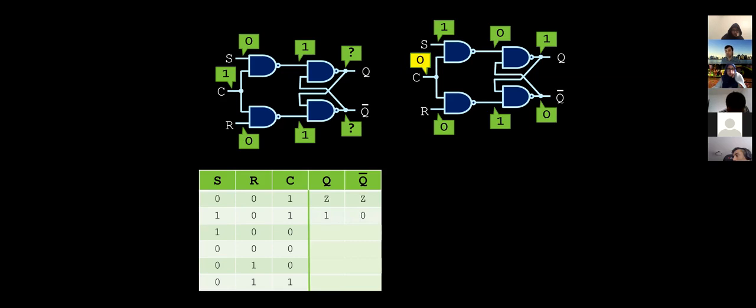Okay, what if I go down with my timing? I go from a positive 5 volts or something to 0. Well, let's see. This 0, 1 is not going to affect this one. This is still 1. So with this 0, 1, this is still 0, this is still 1, so I'm going to get 1 here. And here I was still getting 0 and 1, so it's still going to get 0, and this is still getting 1. So I'm locked at the previous state. This is what the clock does for that circuit. When I go from high to low, I'm just stuck with the previous values. I can't really move, okay? So the values are stuck at 1, 0. And that's part of the memory theme. It's stuck there.